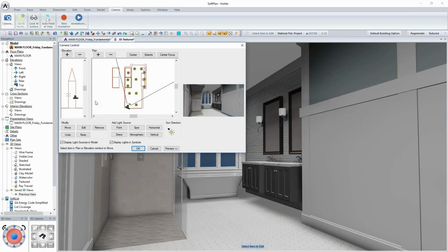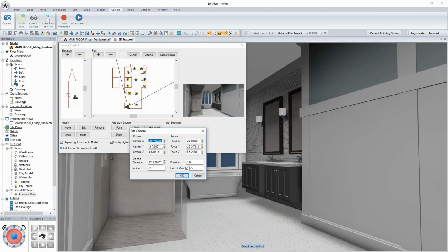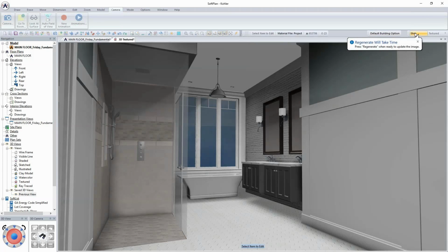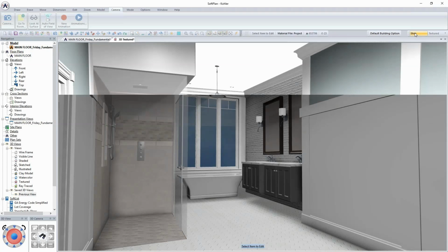One more thing I will probably do, and this is just something I do before I hit go on this, is I will oftentimes come in. This is kind of an old school method of doing the camera option, but I tend to set this so that it's realistic to maybe someone standing that's 6 foot, 6'4", whatever it is, and what their field of view is going to be, so that we're not looking up at the model, but actually standing at a head height and looking towards the model, and then just beginning to let this regenerate and show us the model.